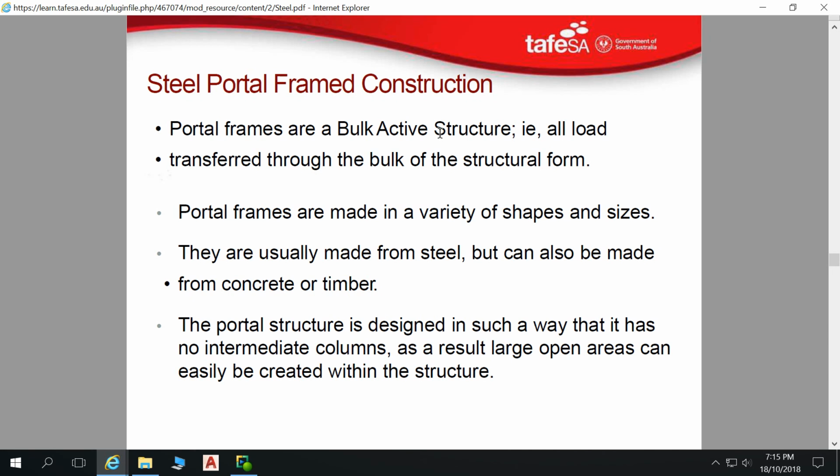Introduce a portal frame, you don't have to have that cross bracing, so you can have a big window in there. If you have to have that cross bracing there, well, you probably don't want to have a window behind the cross bracing. It's pretty ugly or pretty bad detail. So that's a really good use.